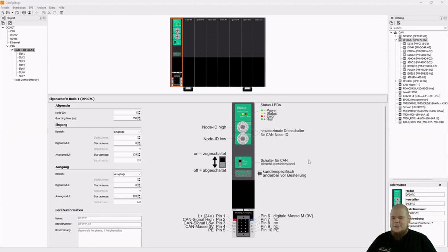An interesting story is also that node failure can occur after a power cycle, i.e. when the machine has been restarted or similar. How can that be? If somebody played with the node ID before the power cycle, nothing happens at first. But when the node is restarted, it reads itself again and finds out that it doesn't fit with the selected number, so it is not configured properly and stops working.